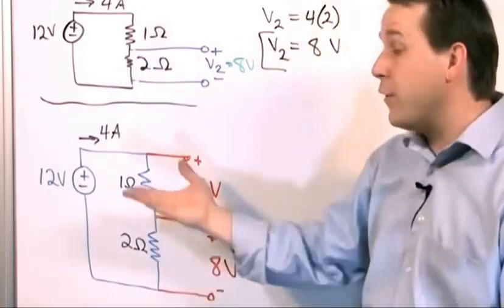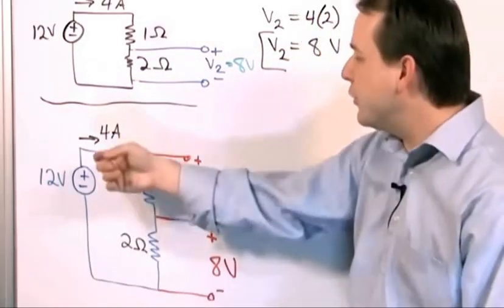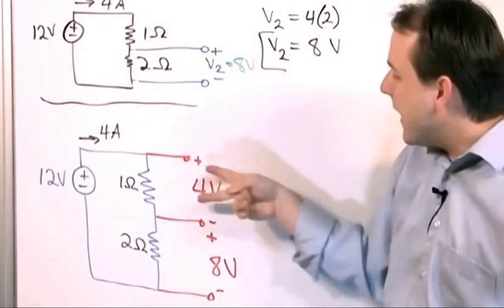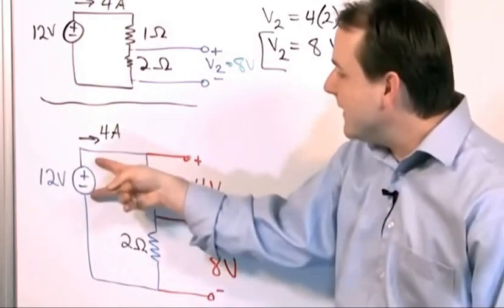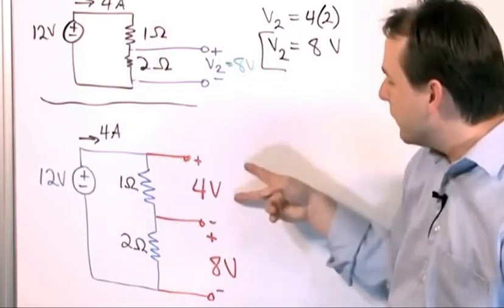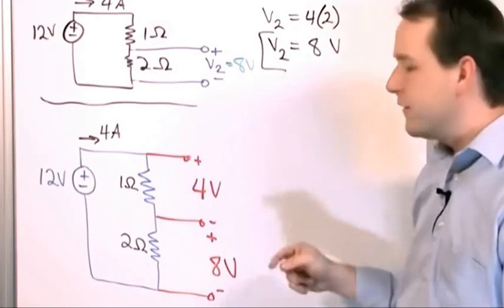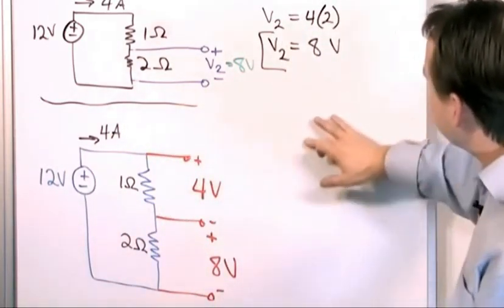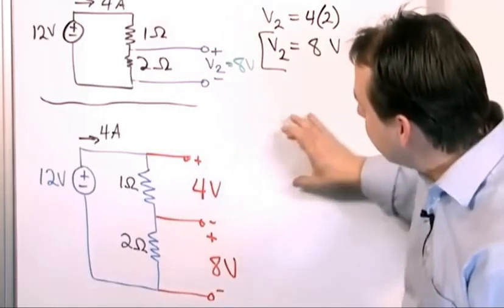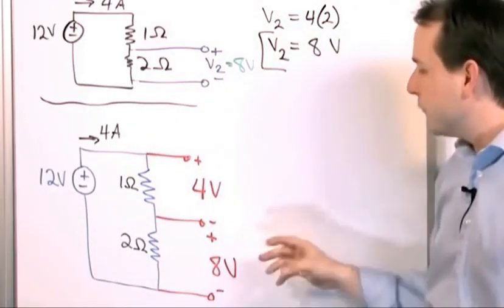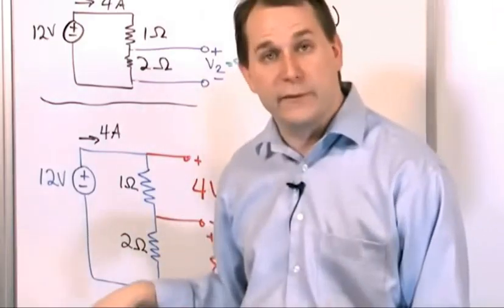So if all you had was a 12 volt battery, then you could construct a voltage divider like this to basically have 4 volts here. You're basically taking the source and forcing it to be split up so that 4 volts lies across this guy, 8 volts lies across this guy. So I could take my delicate circuit over here and wire it up right here to the 2 terminals. The 4 volts would then be supplying my little delicate circuit. The rest of the energy would be going through over here.